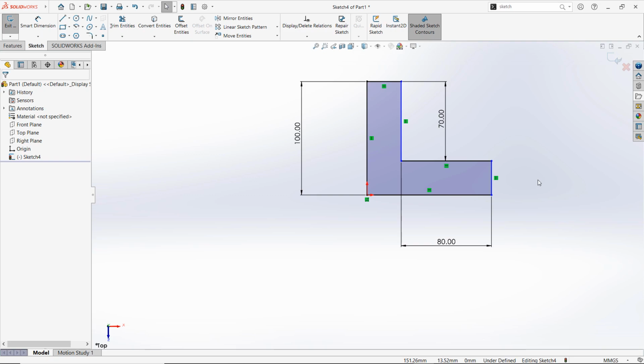I've got two different line colours in here. What's that all about? Some of my lines are black, some of them are blue. What does that mean? Well, these colours are actually pretty key to SolidWorks sketching. Now what we always want in a finished sketch is always black lines. We want everything to be in black lines.